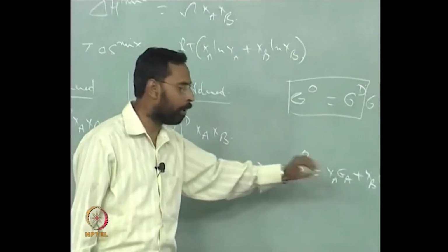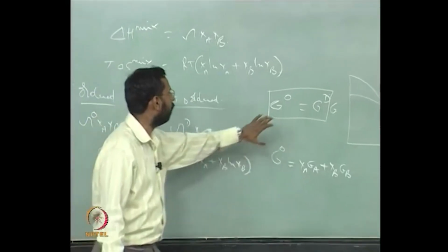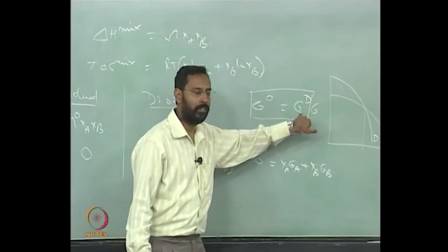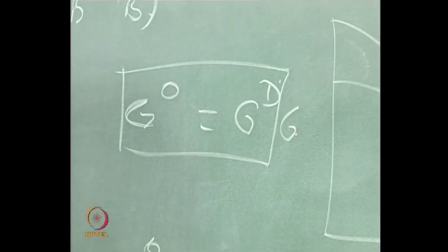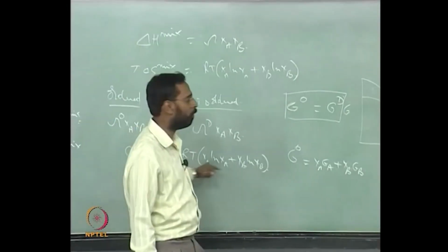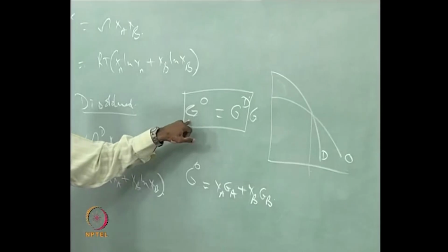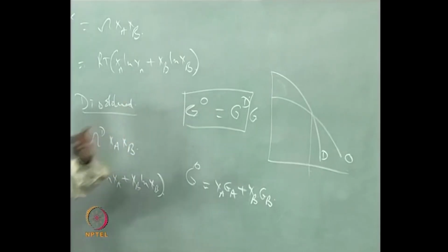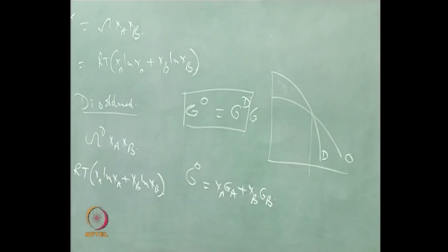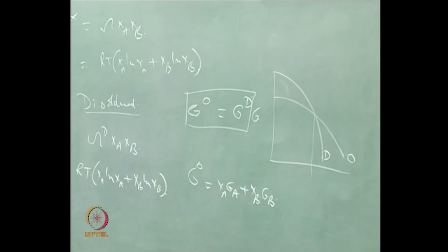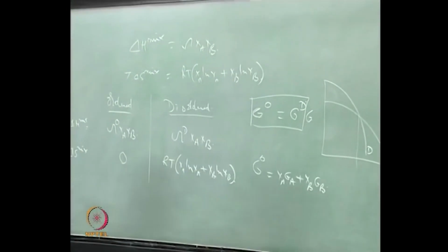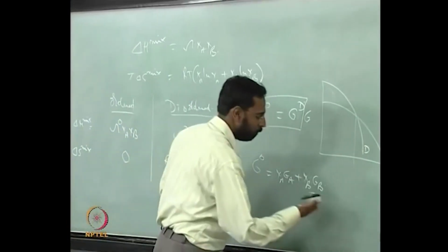You will have thermal entropy coming in the case of the disordered, and along with the thermal entropy you will also have configurational entropy in the disordered, whereas in the ordered case you will not have a configurational entropy, you will only have the thermal entropy. Once you consider that, the expression becomes easier and more correct. Some of you have not considered it, I want you to remember this in future.